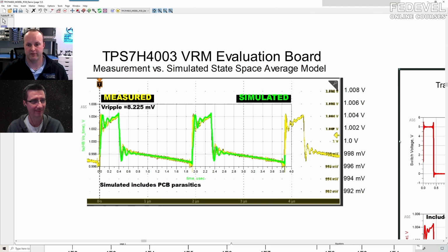They're 100% identical. 1.008 is up here, 1.006. All the axes are 100%, 4 to 4, 3 to 3, 2 to 2, 1 to 1. So you can even see that the ripple matches verbatim. Again, that goes back to having the gain value set correctly because we made the measurement-based model. You do not have to do that if you're not doing this. I wanted to show people that you can get this, and this is how you would do a correlation. You can see the ringing in our waveform is lining up with what was measured.